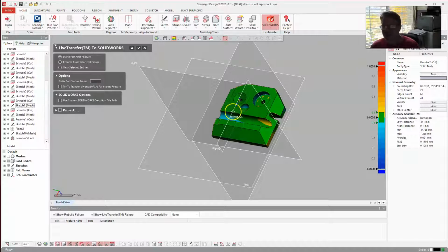It allowed me to do it in GDX, Geomagic Design X, but when I transferred it, it came up with an error because I guess SolidWorks doesn't like you to do that, so they want you to do like a half circle and a revolve cut. So finding little trick tips like that, hence the drawing the half profile on this one, doing a revolve cut. It likes that. If I were to draw the entire profile and do a 360 cut, it wouldn't like that. Or I guess I could do a 180 cut and it should be okay, but I didn't try that.